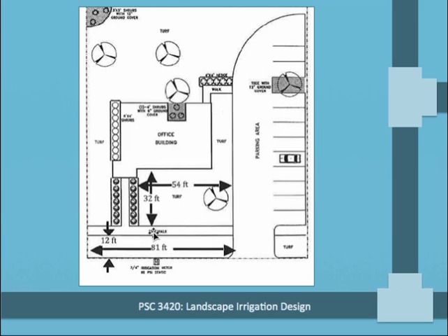Now if you think back to how the different sprinklers were categorized and classified, recall that the small rotors were appropriate for areas from 15 to 30 feet in width. And so mediums, I believe, were 30 to 50 feet, something along those lines. And so my point is just that for this area that is a little bit wider, small or medium-sized rotors might be appropriate. And if you're considering how to select and lay out heads, you'd go through your whole base